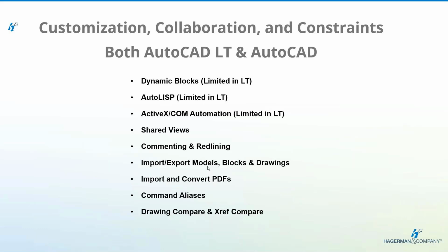You can do shared views for collaboration. You can share your views on the cloud through LT so that other people, including yourself, clients, vendors, coworkers, whoever, can see them, and they can do commenting and redlining. The one difference with LT is you cannot import those red lines. With AutoCAD, you can import the red lines and have it as a backdrop in your drawing so that you're literally seeing the red lines on your screen with the drawing.